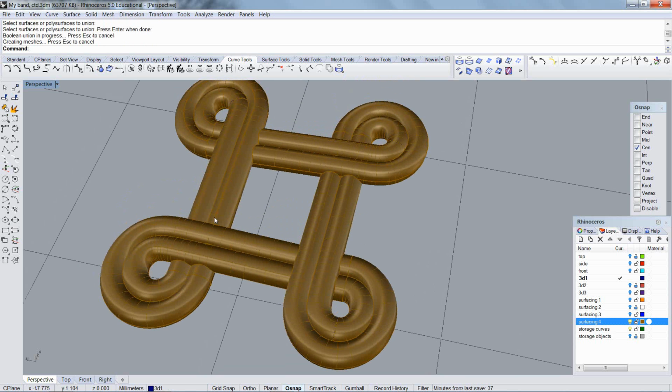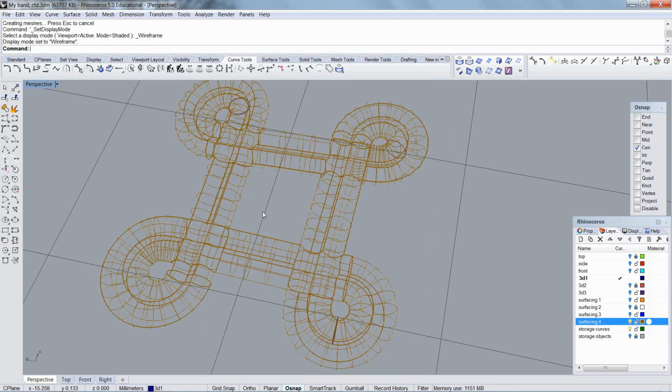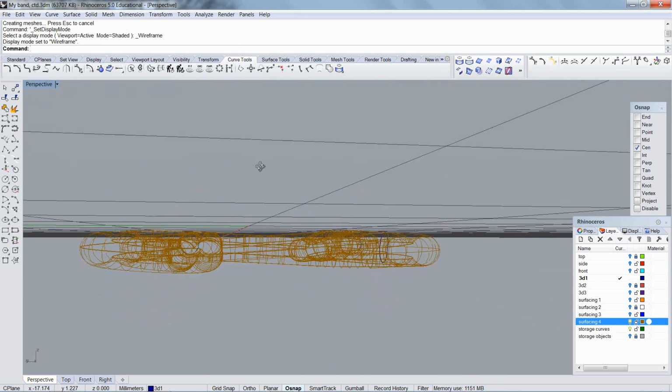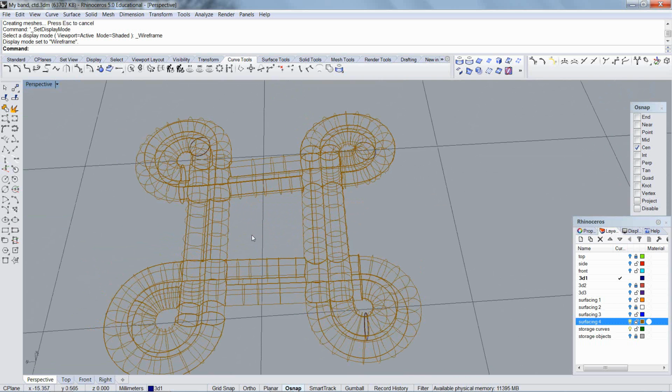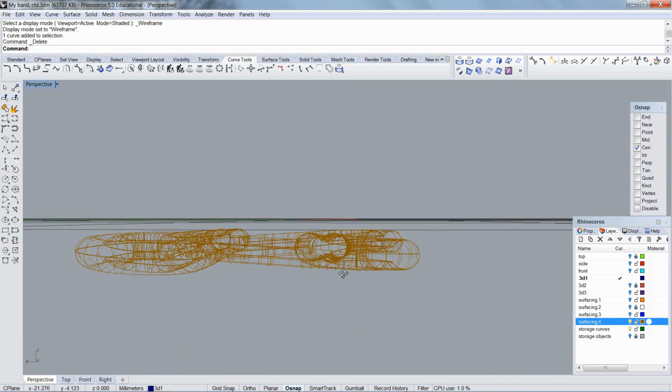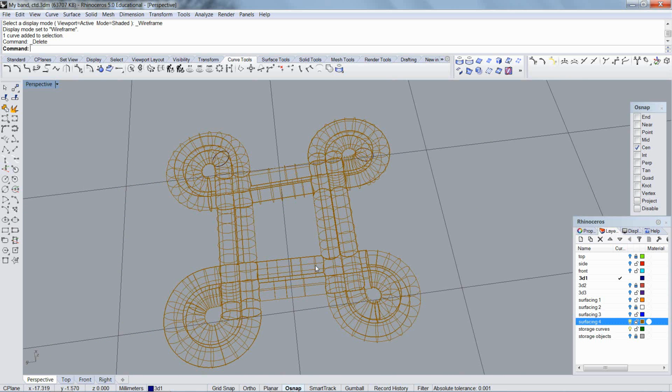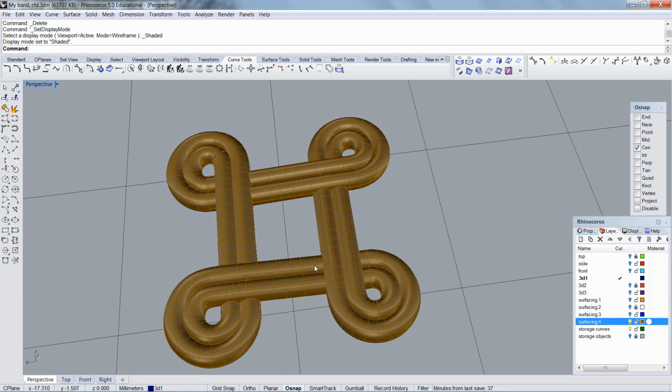Okay. Now, since neither one of those had a problem to begin with, the combination of the two should also have no problem. That's important. What I just said, I'm going to repeat it, because both of those two original parts had no problems with them. No self-intersections, no coincidental caps. The combined object I make from the two shouldn't have any problems. Okay? If I had left the problems in the other two, clogs in the drain, self-intersections, but I'd Booleaned them and Rhino said it was fine, when I put the two of them together, I would just multiply the problems.